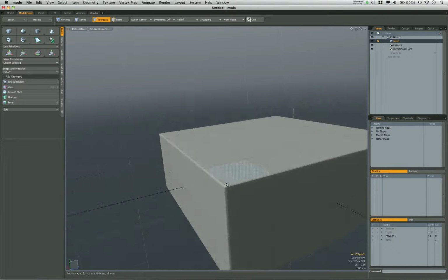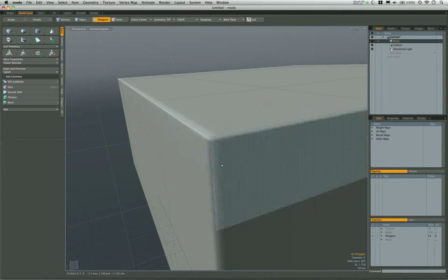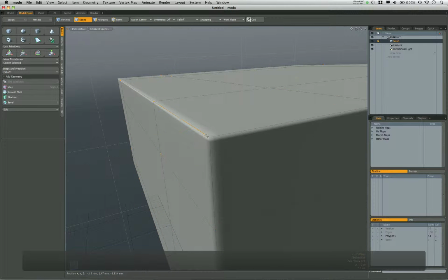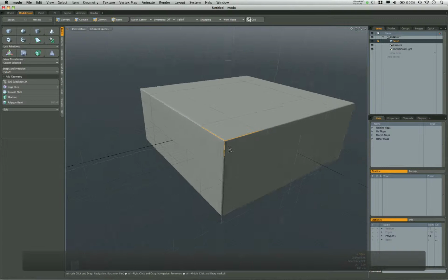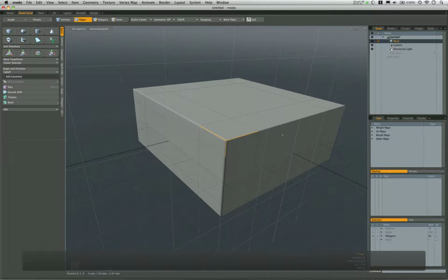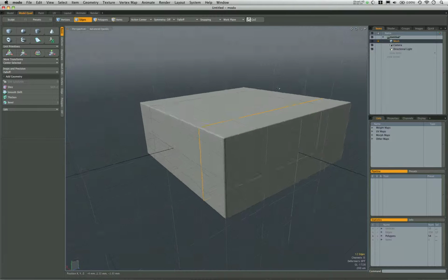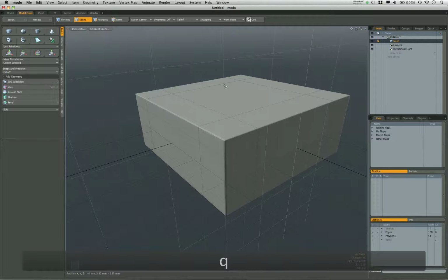With a subdivision surface, if we want to keep something sharp, what we'll want to see is an edge that defines the actual physical edge, and then we'll need edges on any side surface that will sharpen up that edge, like this edge here or this edge here. All right, so now we'll look at how to add on a circular piece on top of that.